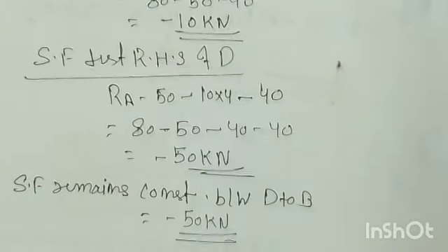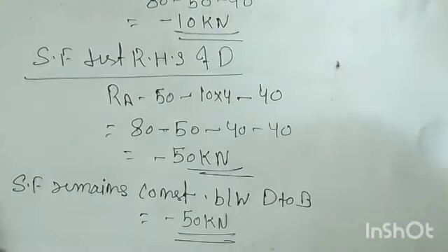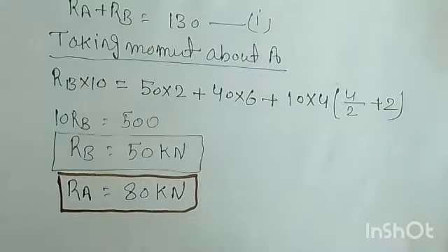All right. Now, as I told you, between C to D the shear force changes its sign from positive to negative. It means between C to D there is one point where the shear force becomes 0. That point we have to find first. So now, you can wait.